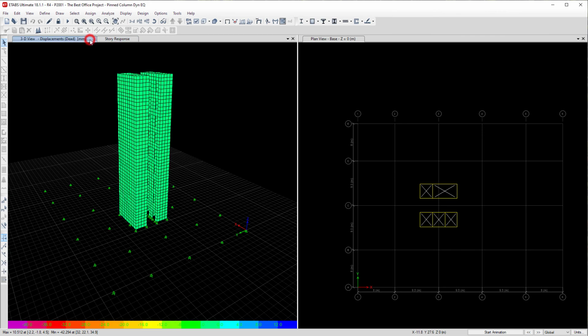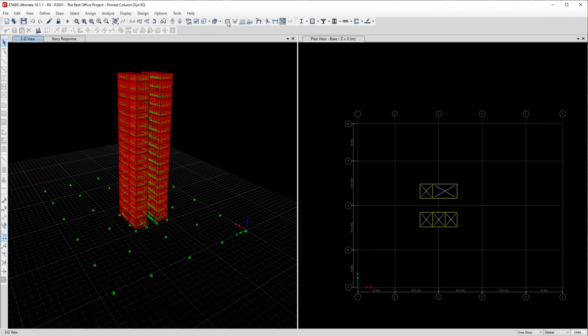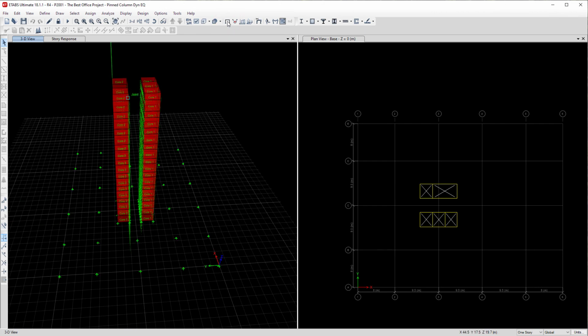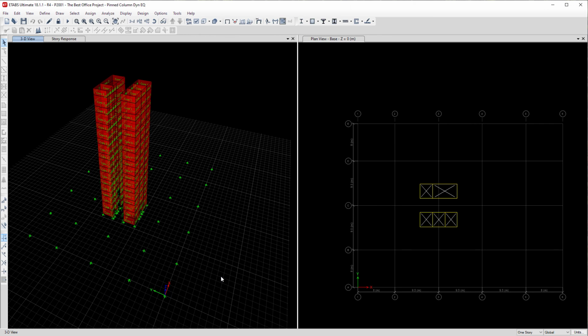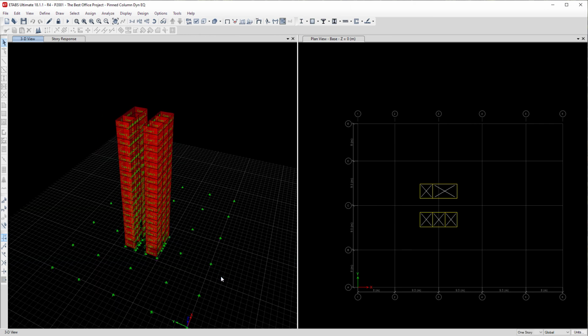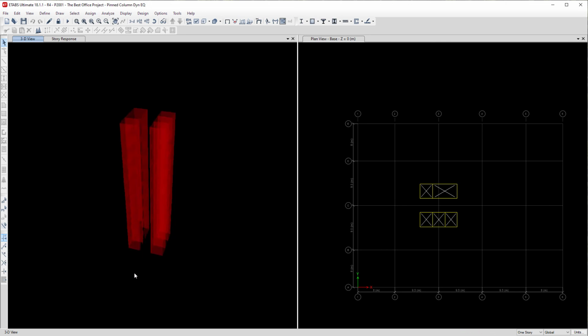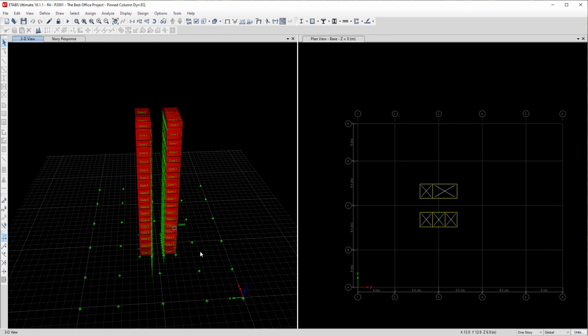So in conclusion, that means that our 200 thick cores work for drift without having to thicken them to 300 thick, and without having to add the header between the two cores using the dynamic analysis. In comparison, when we did the static earthquake analysis, we needed to thicken them to 300, and we needed to add the headers just to achieve height on 130, which is still worse than height on 150 or height on 140 that we're getting from the dynamic analysis.